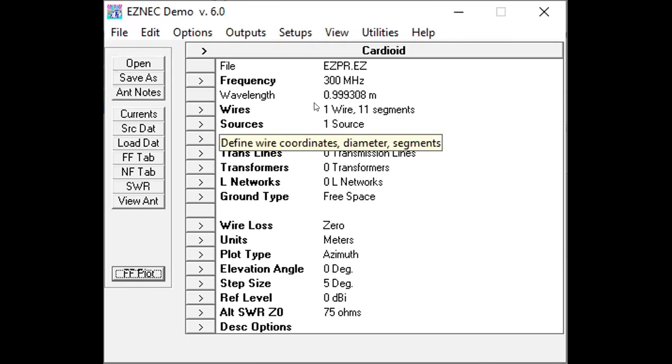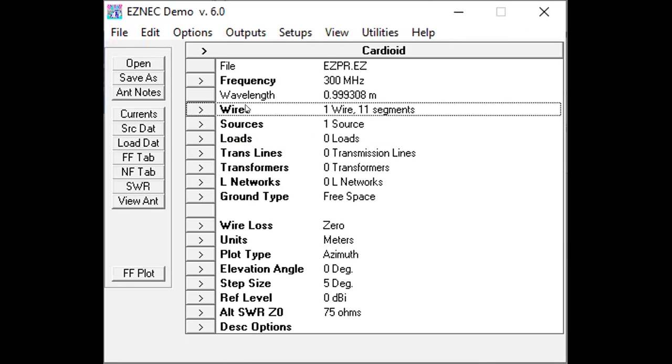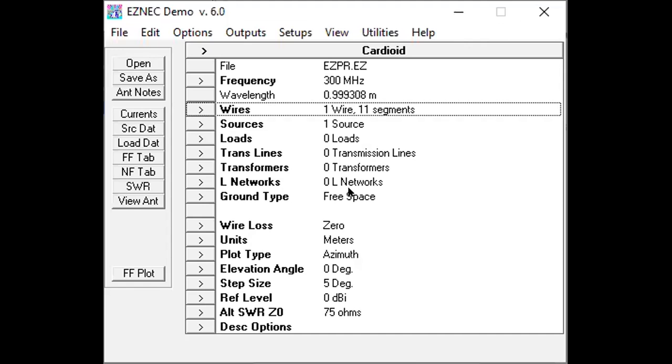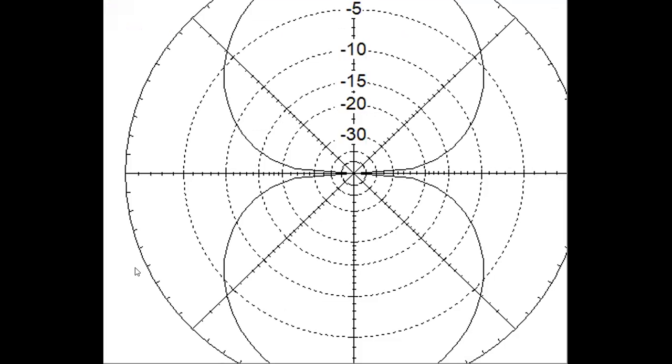Now let's design for the next length. Again go to the wire. Now let's change it to minus 0.25 and plus 0.25. See, again the lobe. See, the widening of the lobe is there. That is the difference. But there will be no side lobes added because the length is small.